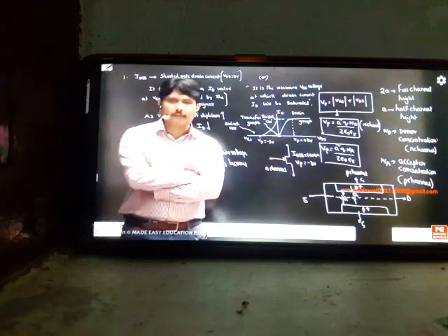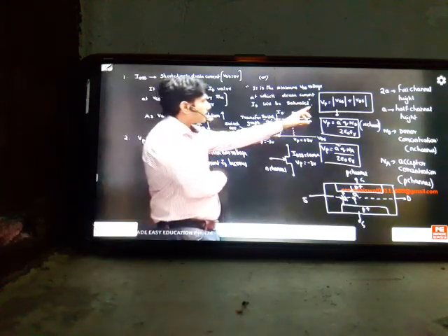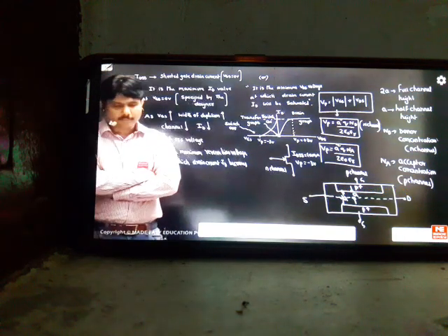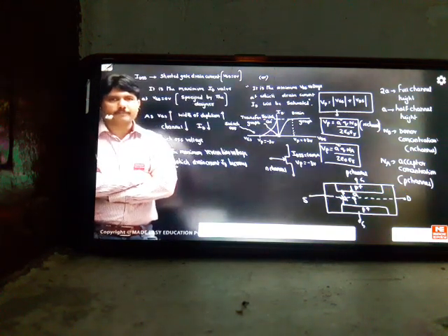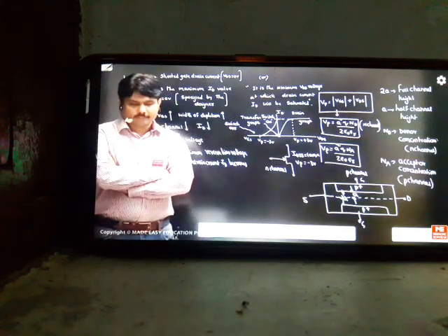Shabnita, pinch off voltage will not always be positive. It's only the modulus, to understand how much the pinch off voltage is. The examiner has already given the pinch off voltage. Only to find any one parameter, we have this equation with us. If you want to find VGS and VDS in your problem, that relation will help you calculate the pinch off value. Otherwise we can solve for VDS and VGS.